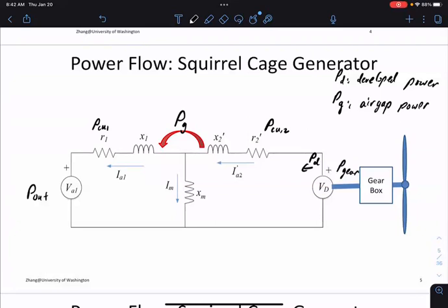If you look at all these things, when you're doing calculations they're just equations. But when you look at this diagram, it's good to think about where you can squeeze. If you want to build a better generator, how will you build a better turbine? Number one, you want to minimize the loss in the gear, the P gear part. The wind power gets multiplied by CP, the coefficient of performance, then becomes P gear. PD has some losses through the generator. Then you have two copper losses.